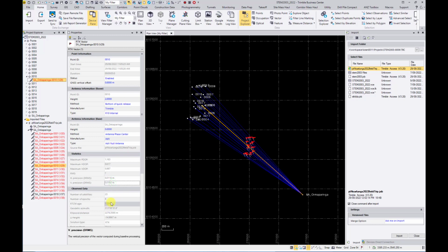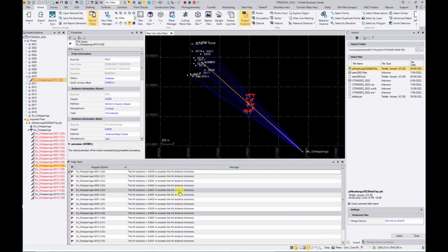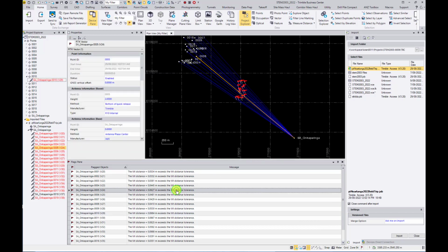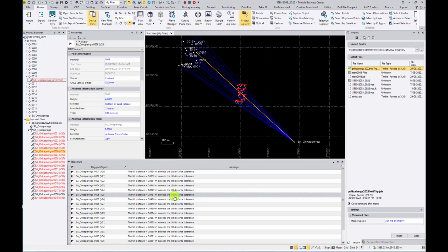And in the vertical we've got at least 2 centimetres, and there'll be a very slight difference in the vertical, but here it doesn't tell you what the vertical error is likely to be. It's only really looking at the horizontal. There would be a very minor difference in the vertical, because of course if it's got a slight tilt on it, then the unit would be sitting fractionally lower, but it would only be millimetres.